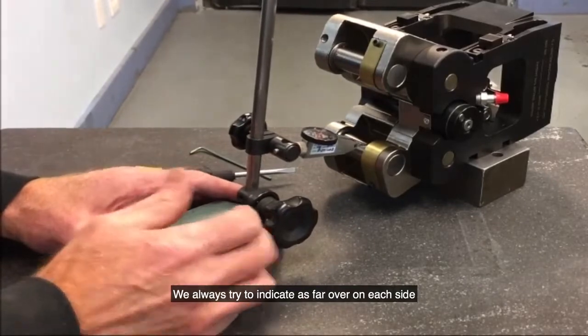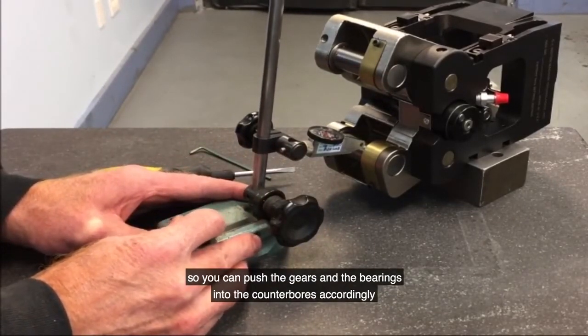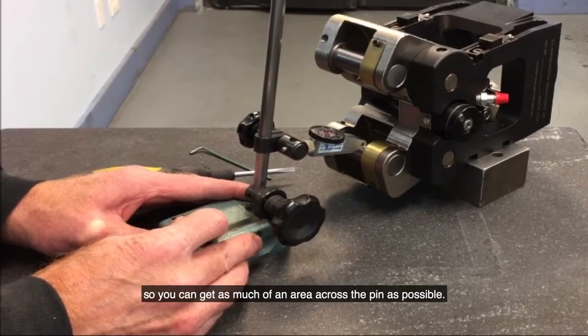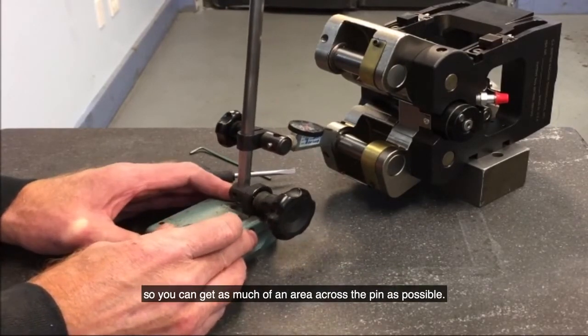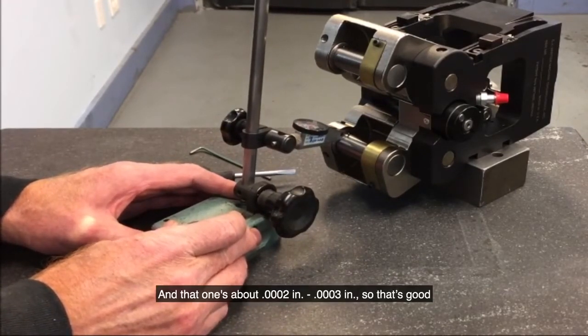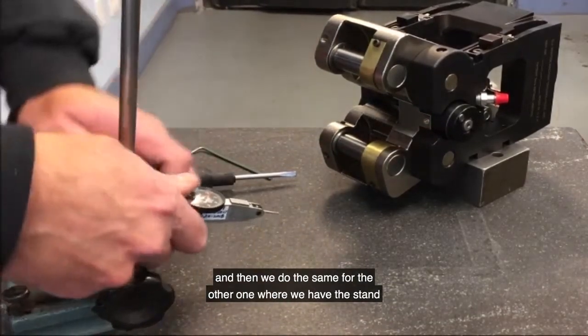We always try to indicate as far over on each side so you can push the gears and the bearings into the counter bores accordingly, so you can get as much of an area across the pin as possible. And that one's about 2 to 3 tenths, so that's good. And then we do the same for the other one.